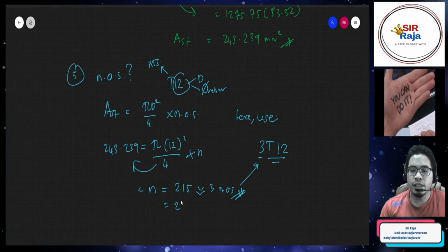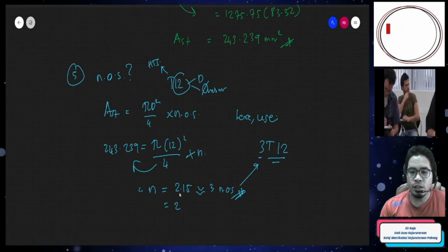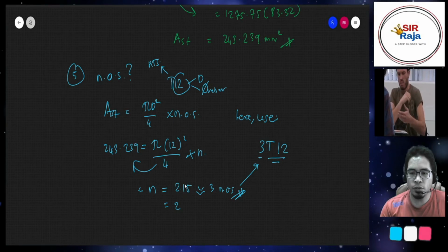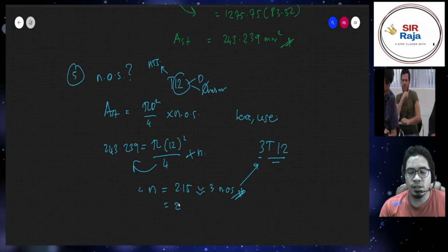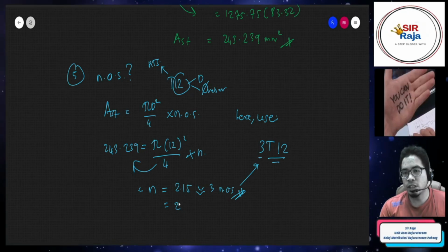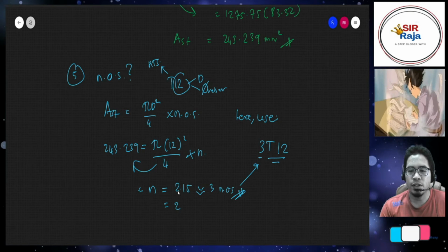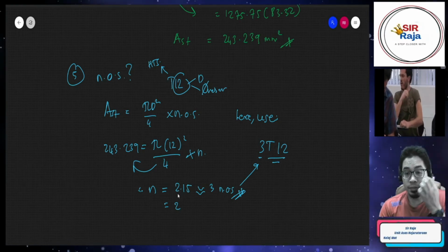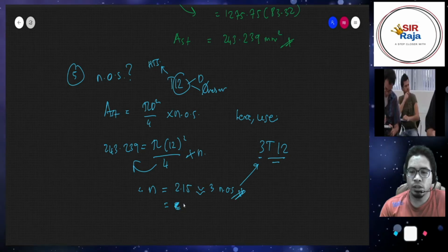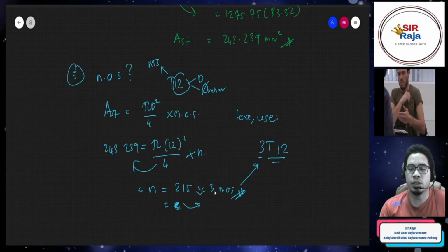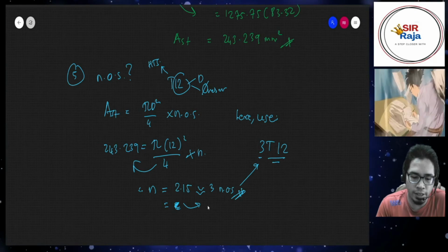But in engineering, imagine that you need at least 2.15 number of steel, and then you use 2. That's gonna make your structure fail because you don't have enough steel. So instead, we're just gonna round up to the bigger one, which is 3. That's the idea.